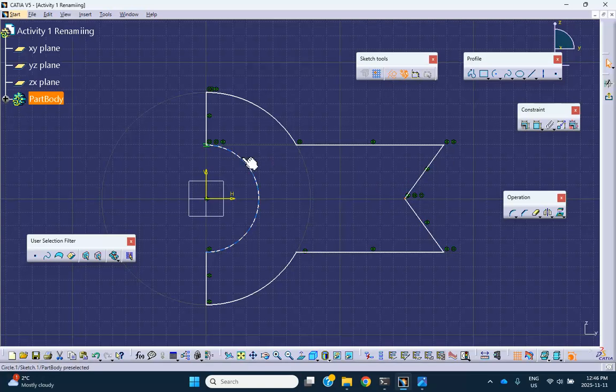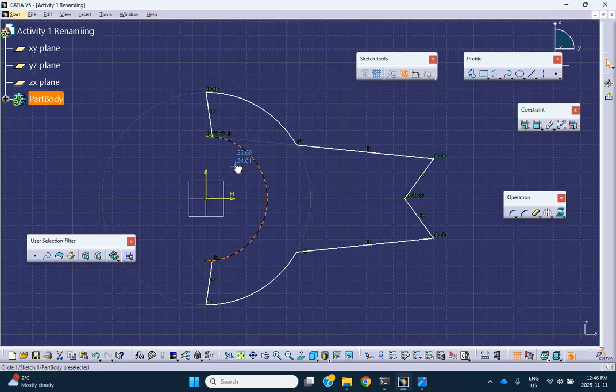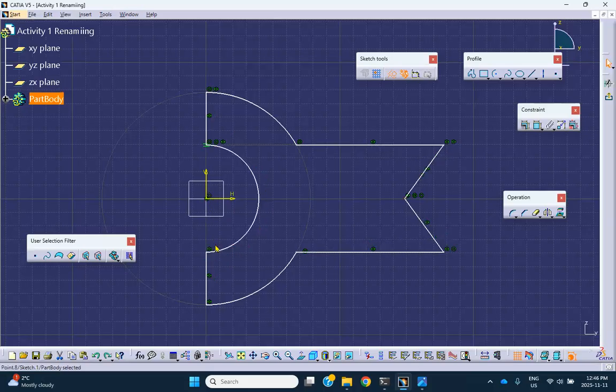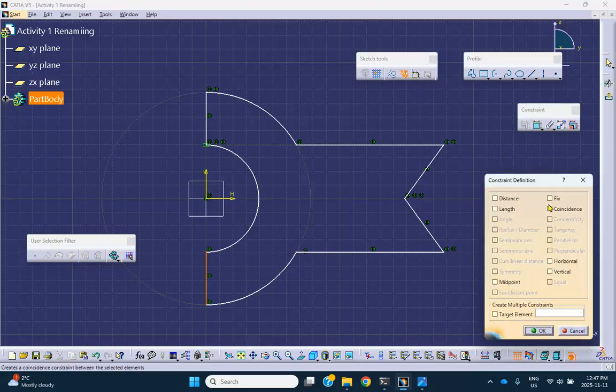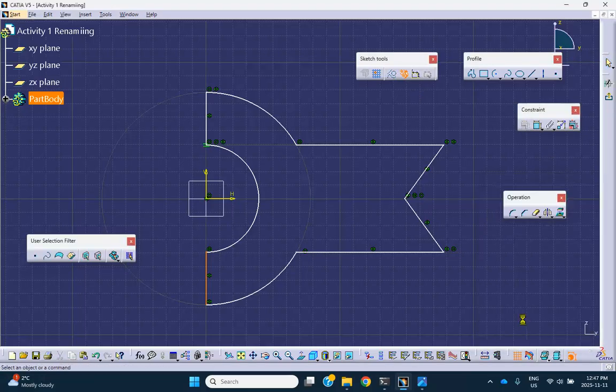So for example, if I select this and move it, everything should move together, maintaining symmetry. Or if I take that circle and, oops, we have a problem here. So notice that the reason that's happening is that these are not coincident. Okay, so Control Z. So we can make this point control that point from the line below it, or at least this line, can make them coincident. It's always a good idea to check these things, make sure that they work the way they're supposed to.